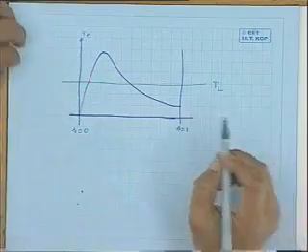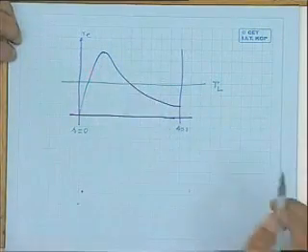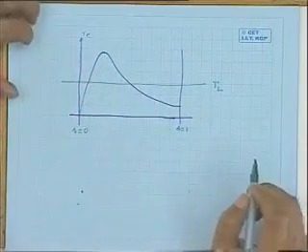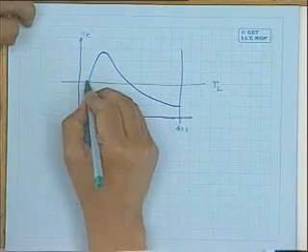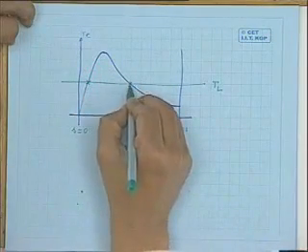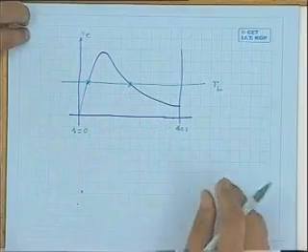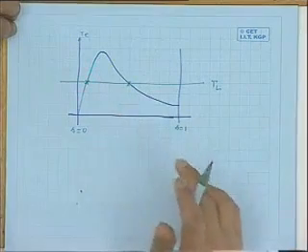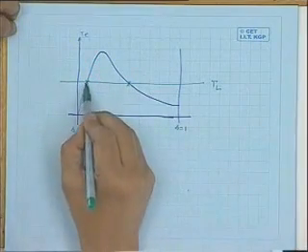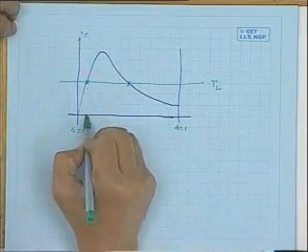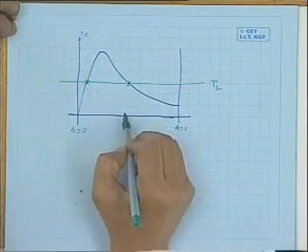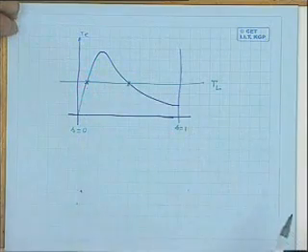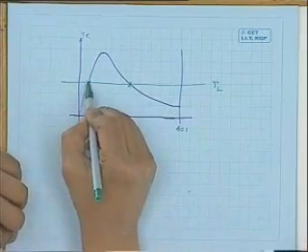And suppose this is the load torque present on the shaft of the machine, and this is the electromagnetic torque developed by the machine. What I am trying to tell is, the operating point could be this one as well as this one. Either of these two can claim to be the operating point. That is, it appears machine can operate at this slip or at this slip.